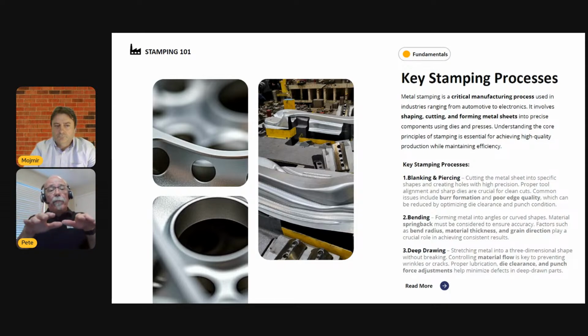So as that flange is being compressed, it's actually thickening. Now, I have some slides that I can show to illustrate this better, but I'm going to wait to the end of the presentation to show those to you. But what's important here is to realize, because of the nature of the deep drawing process, material in the flange will thicken, that thickened material will end up in the sidewall of the article, and additional die clearance is required.